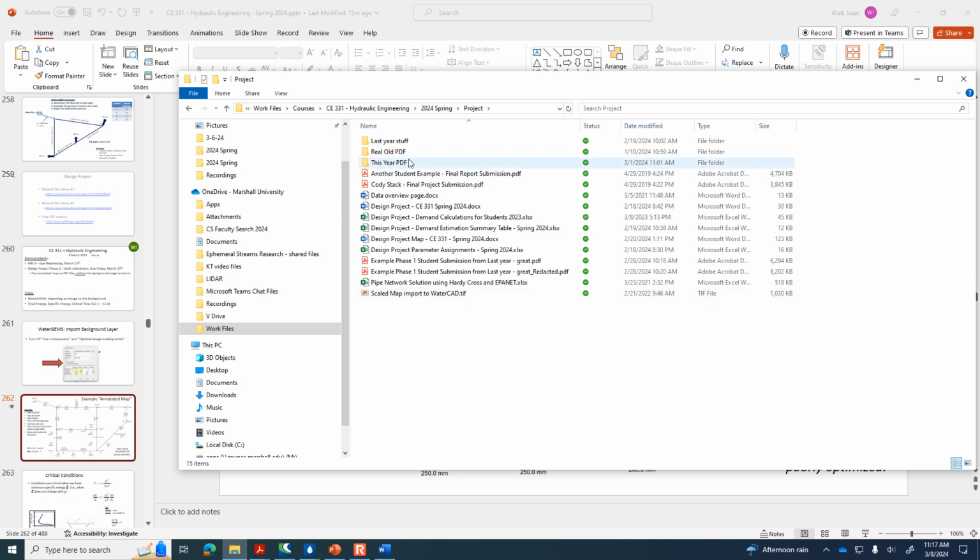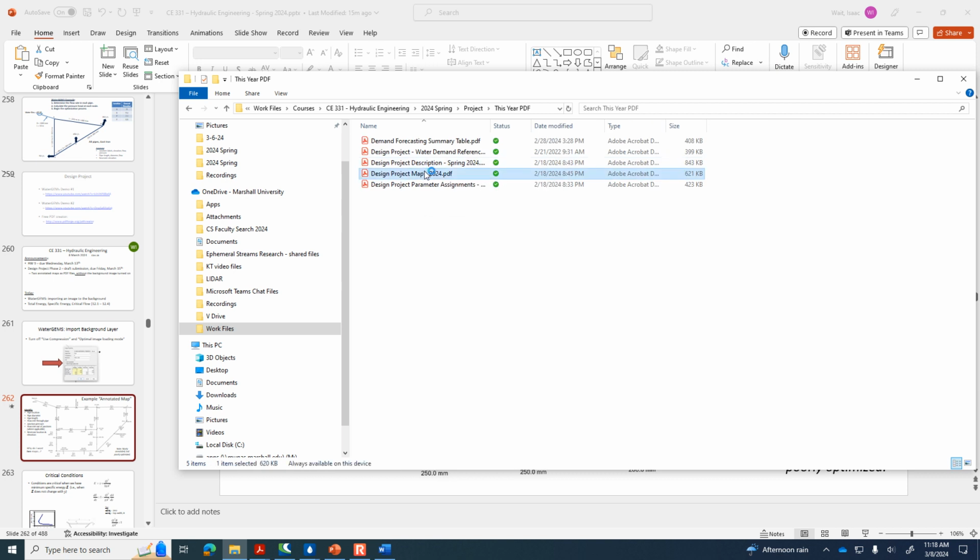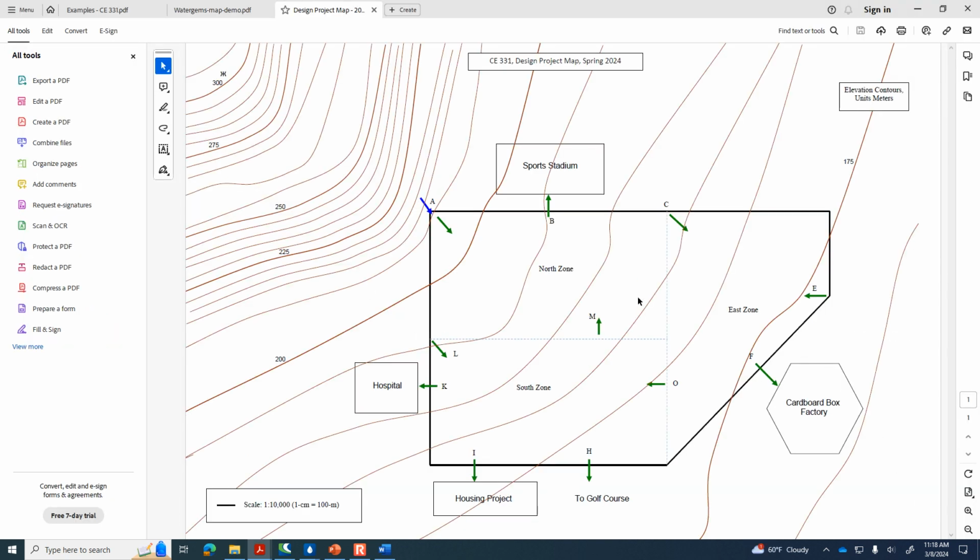But in a real world design, if you're taking a pipeline to a neighborhood that's going to have only very low flow rates or no flow rates for quite some time, then you potentially could be, through a dead end, degrading the water quality or causing precipitation in the pipe as iron and manganese precipitate, clogging up the pipes. But here, we're just saying that at each of these green arrows, there definitely will be demand. And so those concerns that I talked about earlier don't apply. So you can have dead ends here.